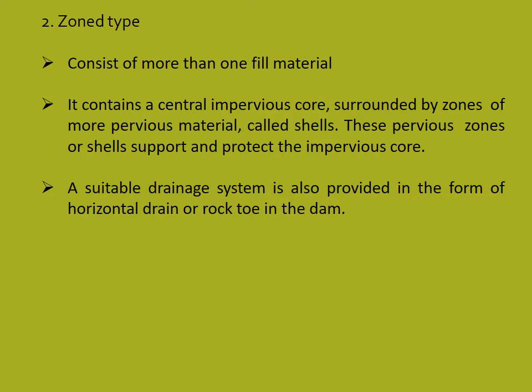It consists of a central impervious core surrounded by zones of more pervious material called shells. These pervious zones or shells support and protect the impervious core. A suitable drainage system is also provided in the form of a horizontal drain or rock toe in the dam.